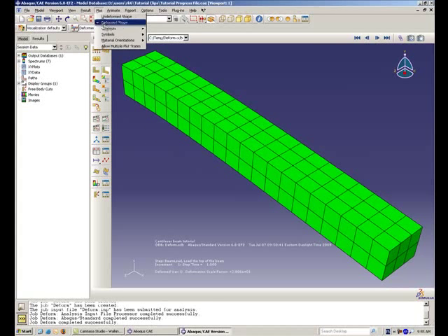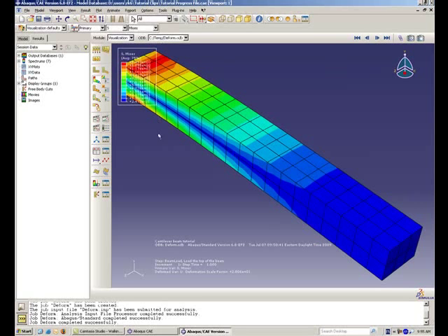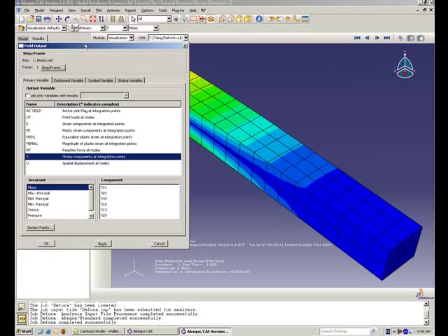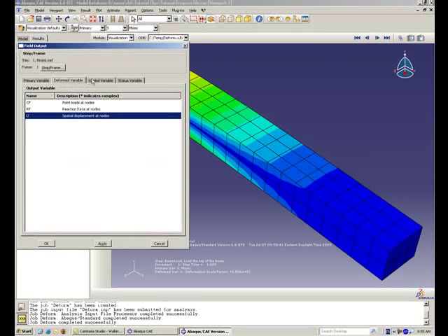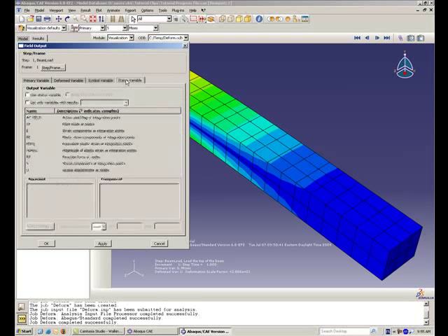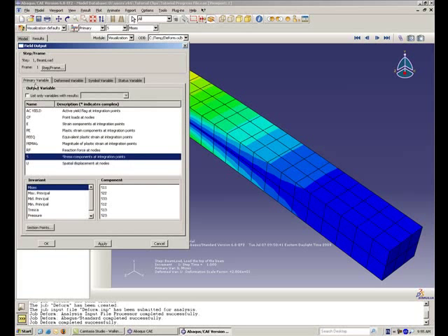Now go under Plot to Contours and choose Undeformed Shape to view a contour plot of the stresses on the beam. You can change the variables displayed by the contour plot by going to Results in the main menu bar and then clicking on Field Output. Try examining this feature. There are numerous ways to view your results in the visualization module, but we will only discuss how to view the deformed post-analysis model and how to show the stresses on that model.